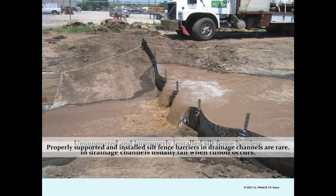Look at that. How many of your silt fences can hold back that much water in a drainage channel? The technique that was used in this thing is called slicing. The fabric is sliced into the ground about 8 inches and held up with metal posts. Just a different approach. There's so many things in there to talk about.